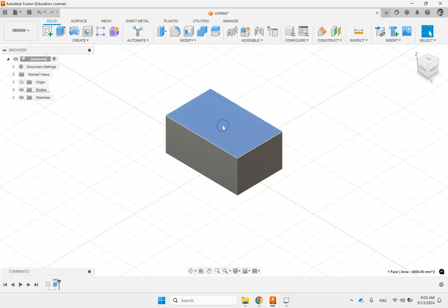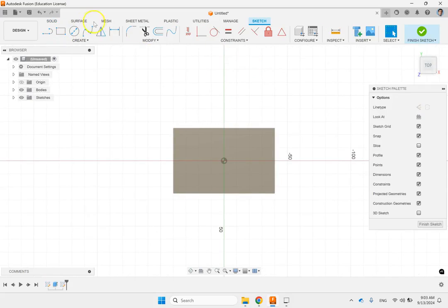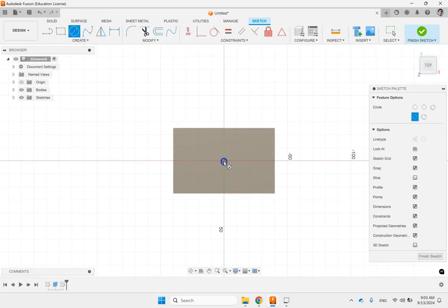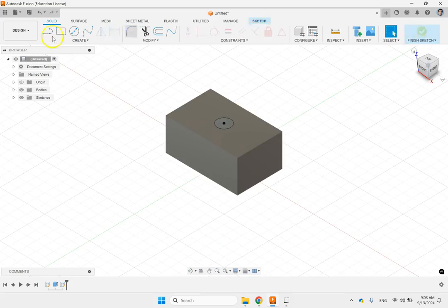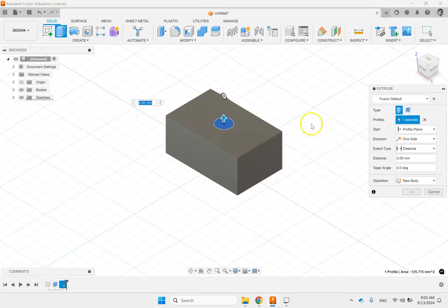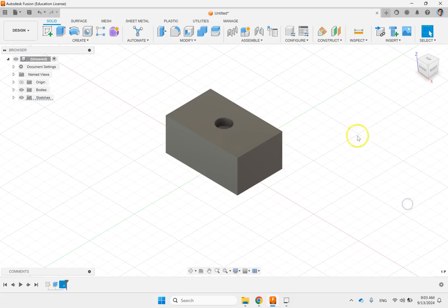Then I go on this top face and start the sketch. And again, I do a circle at origin. And then for the diameter of that, here we use the D tool, get the dimension, and then here we just type in D. Okay, and enter. And there we go. And then we cut extrude this. And let's say the amount of cut extrude is proportional to D, so it's negative, let's say D divided by 2. Okay, 5. There we go.